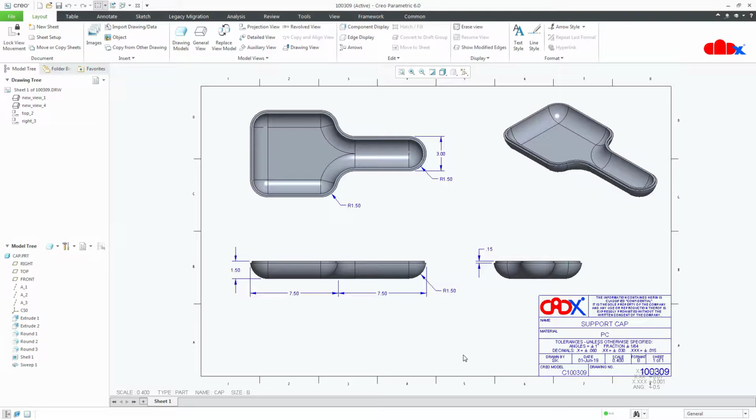To understand a format better, one thing you should always remember is that it includes everything which doesn't change from one drawing to other drawing. That means whatever things you add in your format will be constant for all the drawings. That is why the format includes your title block, because this title block never changes from one drawing to other drawing. Your border also doesn't change, it will remain as it is. Your standard note doesn't change from one drawing to other drawing. So these items come under the drawing format. Now the things which change from one drawing to other drawing come under your drawing template.